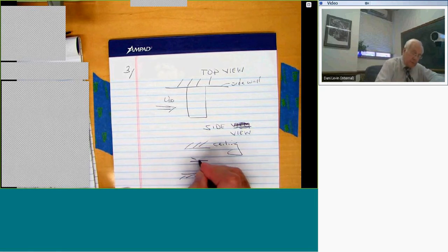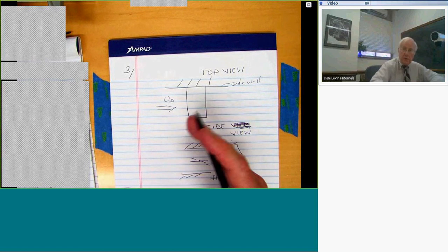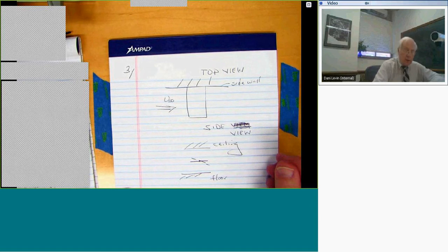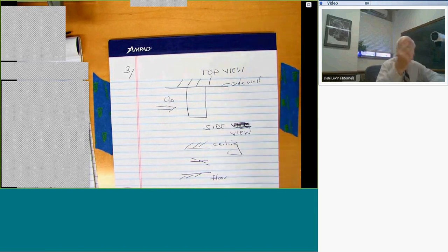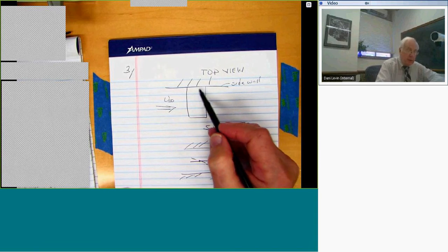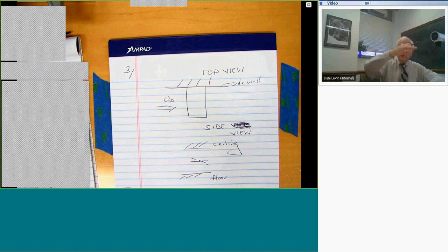So if I assume that this motion in this view is just simple rotation, then if this is an elastic material of some sort, aluminum, steel, whatever, then fixing this wing at this point is equivalent to creating a spring. And that's why I looked at that spring model.